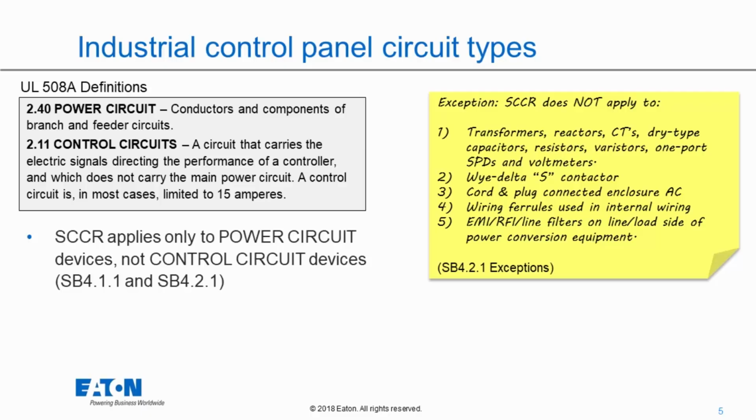So if it goes to an external load, it's part of the power circuit regardless of the voltage, right? It's all about whether or not it feeds a load. You'll see this little sticky note on the side of this slide here, important to note, right? Why we care about power circuit versus control circuit, it's because the SCCR applies only to my power circuit. We get to ignore control circuit devices.